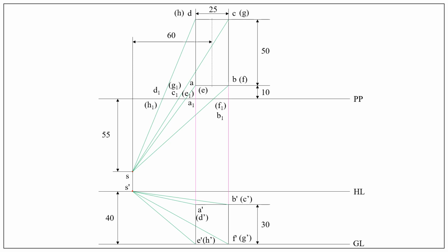Now to complete the perspective view, draw a perpendicular from the point A1 E1 until it meets the line connecting S dash A dash and S dash E dash in the front view, like this.